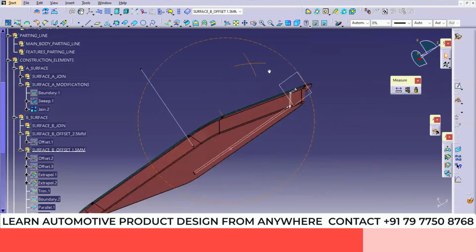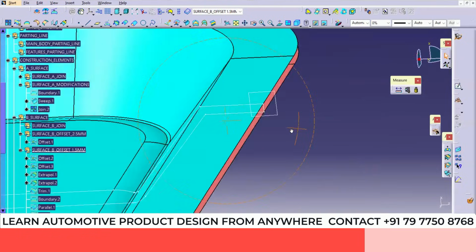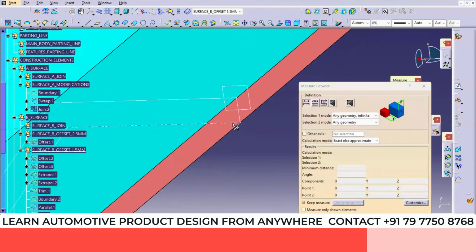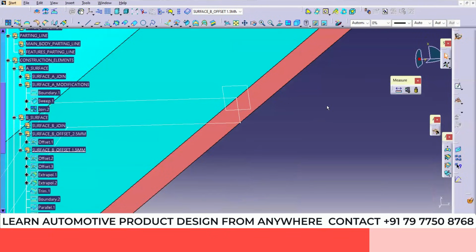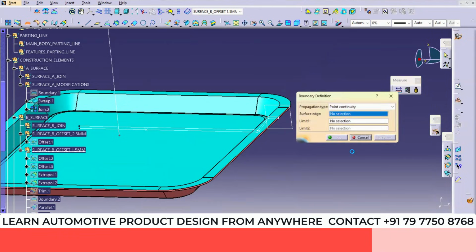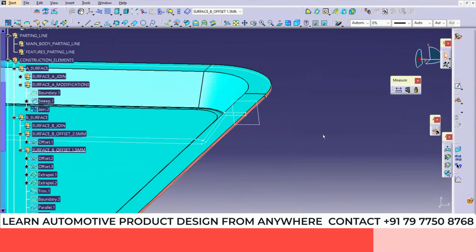Okay. Now next is C surface creation. So C surface we are always creating from the A surface edge, right? So how much is the angle from this to this? It is 89 degree, means 1 degree draft is already given in the section. Okay. So we are not going to apply any draft here specifically. If zero draft, then we can consider our draft. So here I'll create a boundary of this and then we'll use the sweep command now.